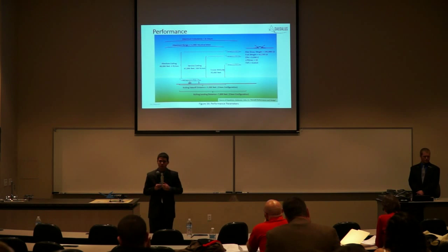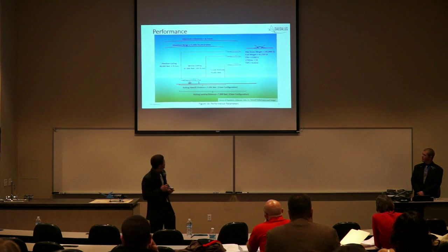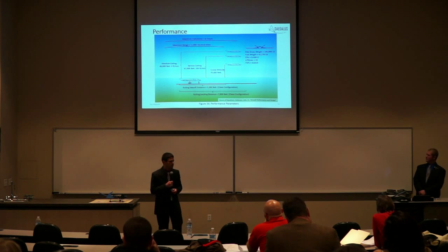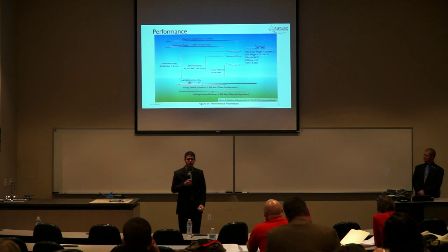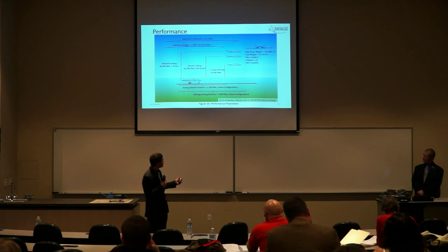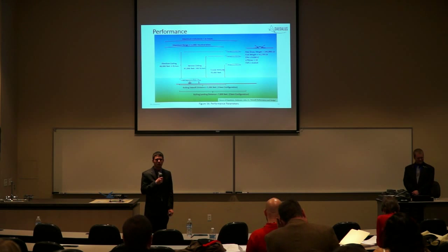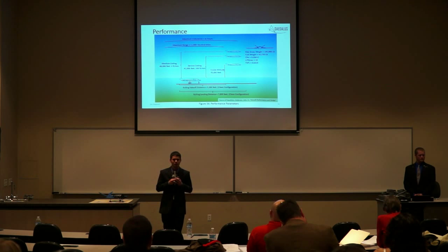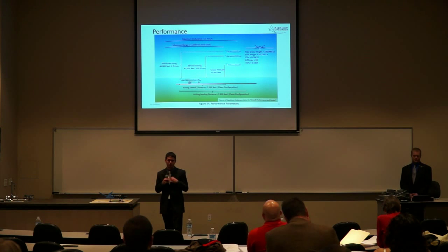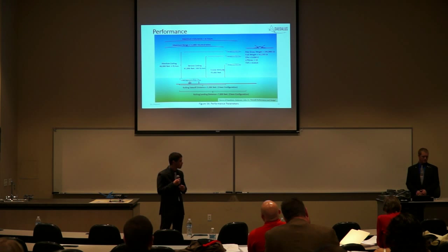Now, the final graph here basically explains the last of our performance parameters. Starting from the bottom, you can see our takeoff and landing rolling distances. Our takeoff distance is about 5,300 feet, and our landing distance is 7,800 feet. These are with clean configurations, meaning no flaps, no thrust reverse, nothing like that.